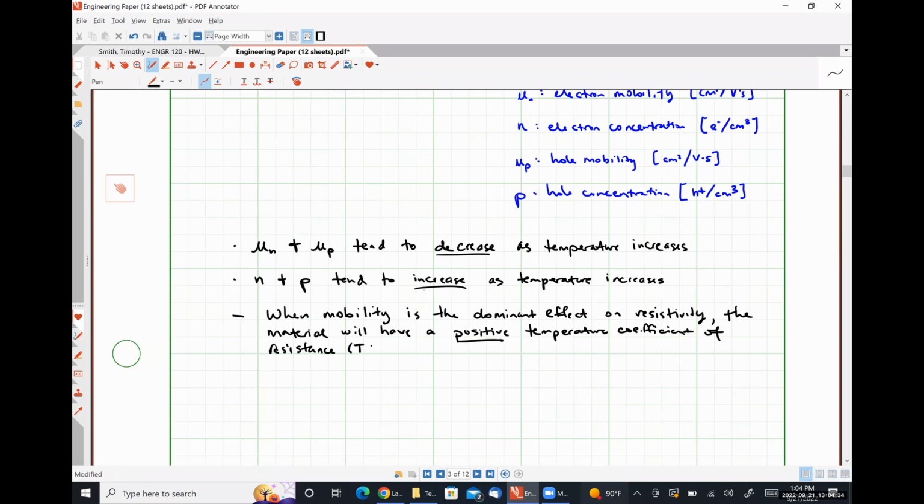And I'm calling this parameter TCR1. TCR obviously stands for temperature coefficient of resistance. The 1 comes about because we're only looking at this on a first order level. If we were to do a Taylor series expansion that governs how this thing actually behaves, we're throwing away everything after the first term, because that amount of math is unnecessary for us to figure out how this thing trends, okay?